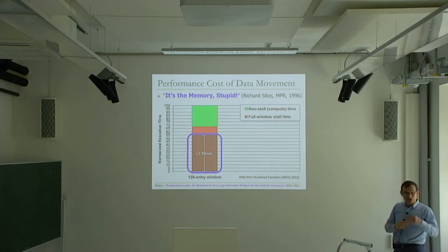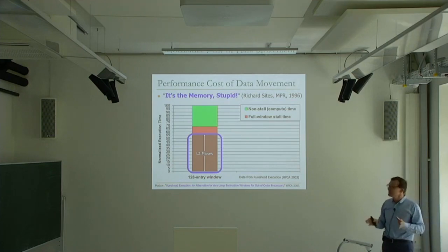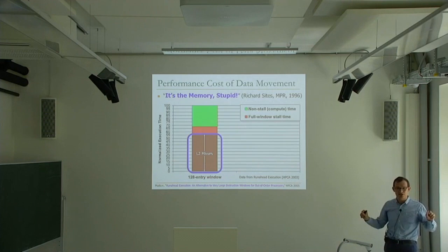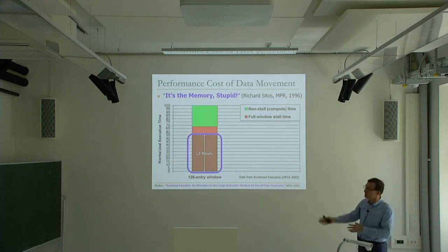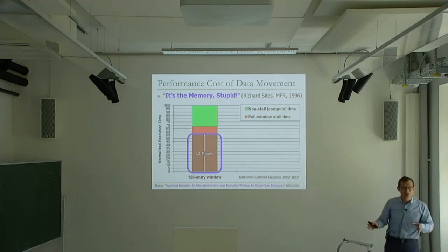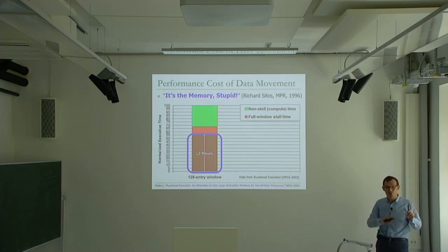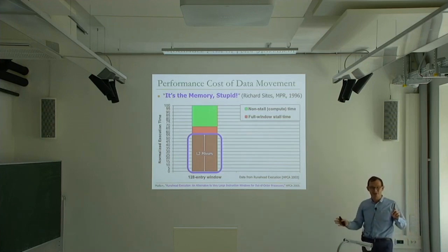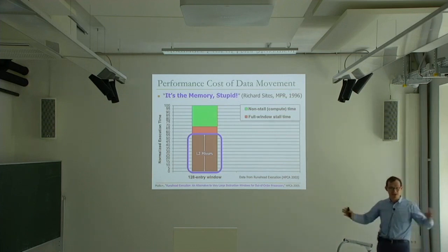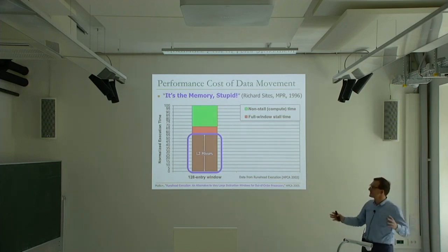So he wrote this one-page article, which is titled "It's the Memory, Stupid." Basically, the gist of it is he says, we designed this processor very hard to finish 4 instructions every clock cycle. And in this important workload that we designed it for, it's finishing 1 instruction every 4 cycles. So it's really operating at 1/16th of its peak bandwidth, right? 1/16th is a very low number.